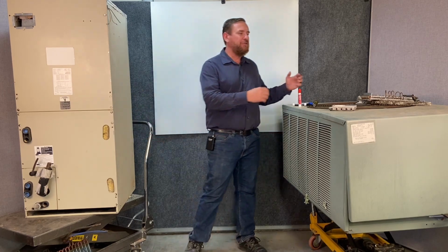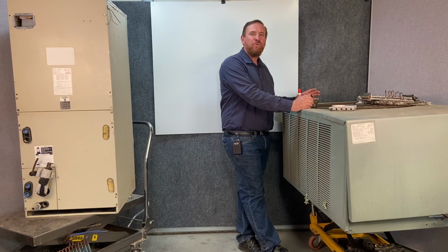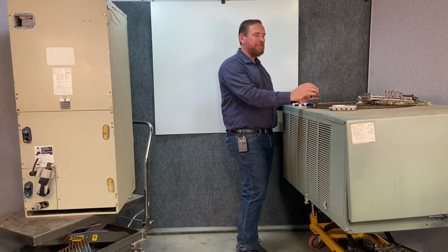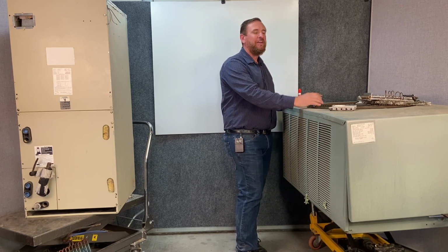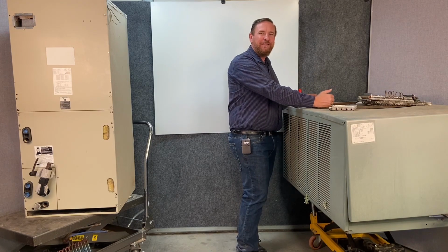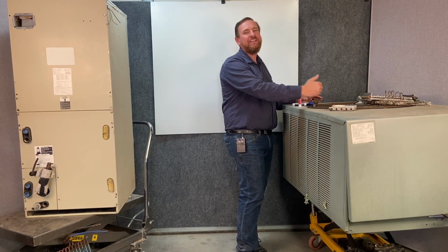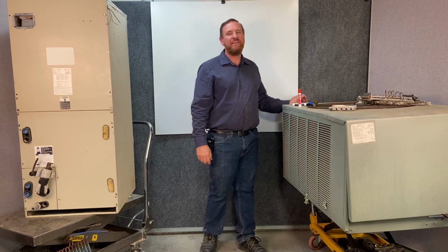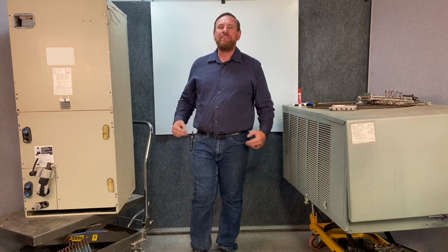Then we're going to have to trick the refrigerant. We're going to have to raise the temperature of the refrigerant to make the refrigerant warmer than the air temperature. So now the refrigerant is warmer than the air, and the heat is going to leave and move to the cooler air outside. So to make this happen, we have a few other things to talk about.